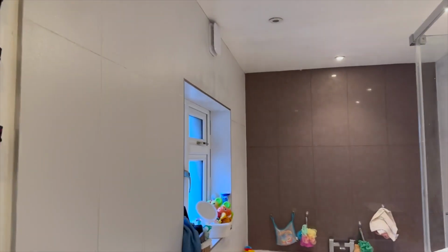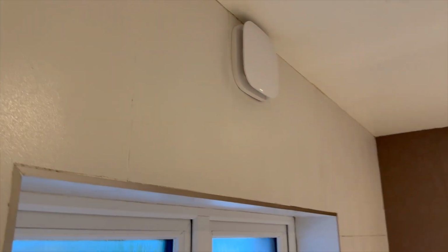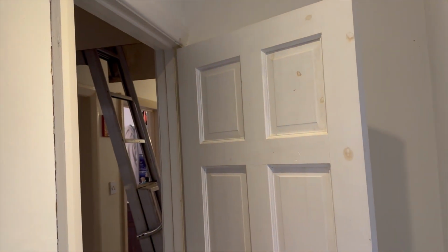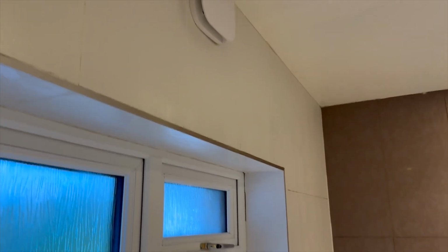So the nearest wet room to the master bedroom is this bathroom, and we can see there's lots of vapour. It feels very humid. There's an extractor fan there. The door was left open, and it should be closed at least until the room is dry. So I'm going to test the extractor fan, see how well it's working. You can actually see condensation in the bathroom. I'm not sure whether this is highlighted, but that's condensation.